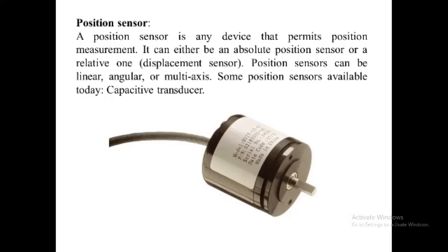When a ferromagnetic material is placed within the eddy current field generated around the inductive sensor, such as a ferromagnetic plate or metal screw, the inductance of the coil changes significantly. The proximity sensor detection circuit detects this change, producing an output voltage, and therefore the inductive proximity sensor operates under the electrical principle of Faraday's law of electromagnetic induction.